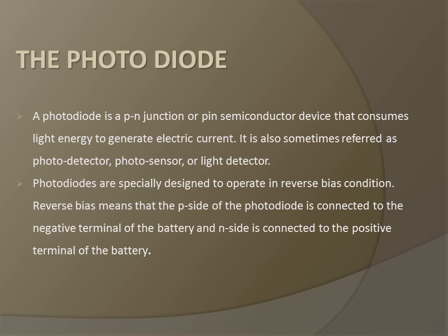This shows the schematic representation of a photodiode, where the light source is incident on the p-type material, and a silicon dioxide mask is coated over the p-type material. There is a surface of cathode and anode, and an n-type bulk silicon layer is represented. A depletion layer is formed over the PN junction, which makes the light rays convert into an electric current.